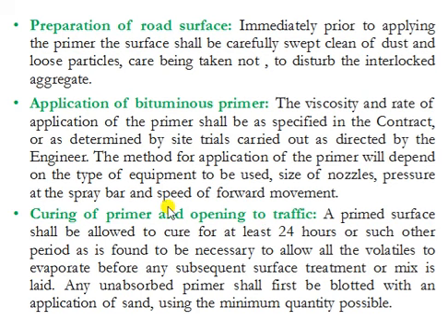So before allowing traffic on the pavement, we should cure the primer. Curing of primer should be done for at least 24 hours. After curing the primer for 24 hours and before allowing vehicles on the constructed pavement, the engineer should check the pavement surface.